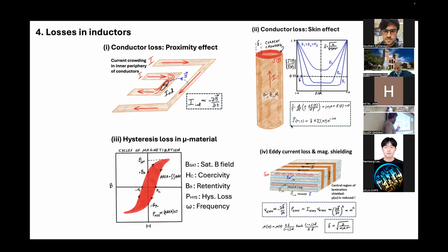And the way you reduce this is you make the material as soft magnetic as possible, because if you make it soft magnetic, this so-called coercive field reduces, and so the area under the curve actually reduces per cycle. So that's again the reason why you use these soft ferromagnetic materials, because they have a very low area under this BH curve, right?